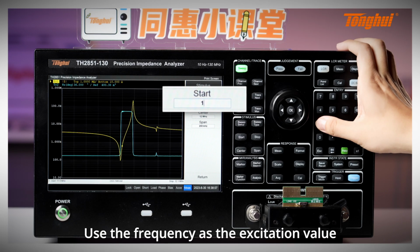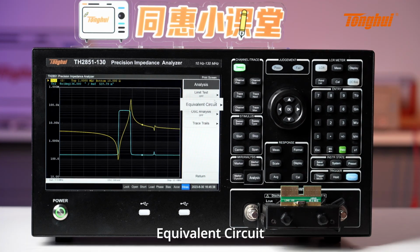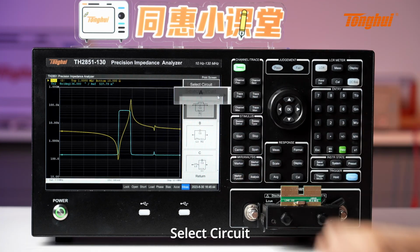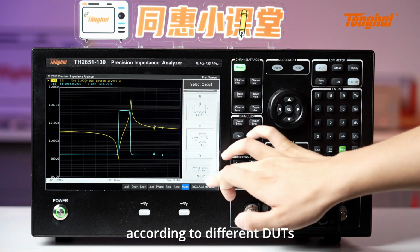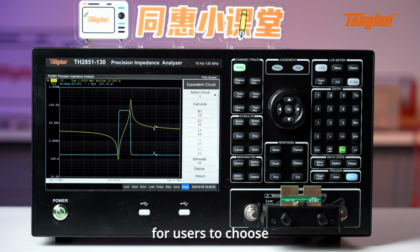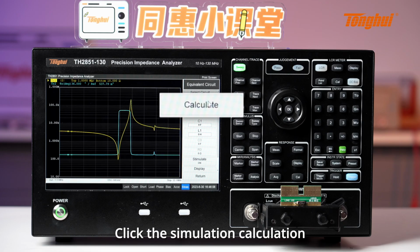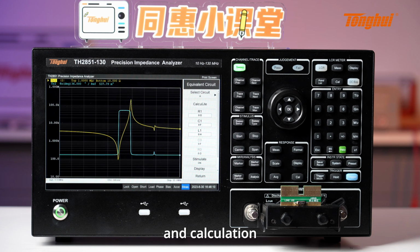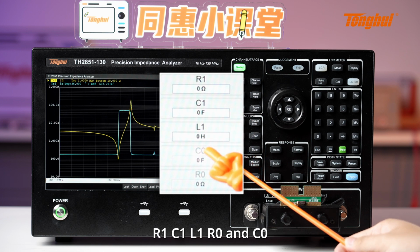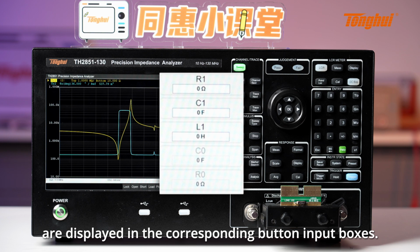Use the frequency as the excitation value to scan the curve. Press Analysis, Equivalent Circuit. Select Circuit in sequence. Equivalent circuit models according to the different DUTs will provide the following models for users to choose. Click the Simulation Calculation to perform equivalent circuit analysis and calculation, and the calculated parameters R1, C1, L1, R0, and C0 are displayed in the corresponding button input boxes.